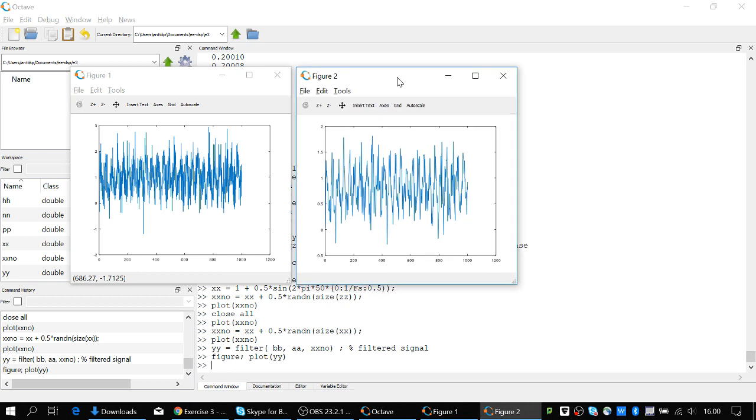So we have a low pass filter which does not affect the constant value. It's still 1-ish, around the same value. Not quite. There's a reason for that one. But now you can see that varying component, the sinusoid, much better. Not perfect. It still has some noise, because I added some wide spectrum noise, and I'm cutting only basically the upper half of it.